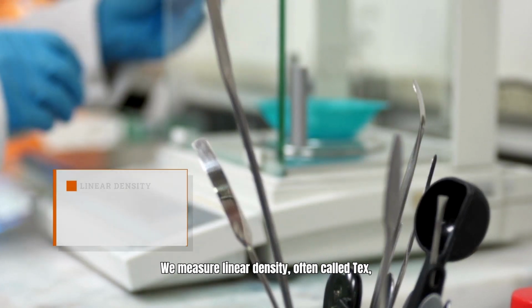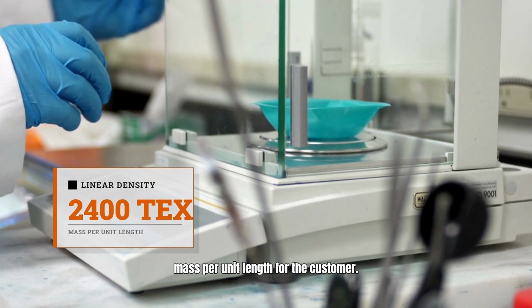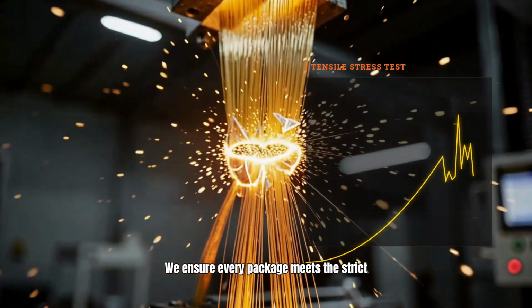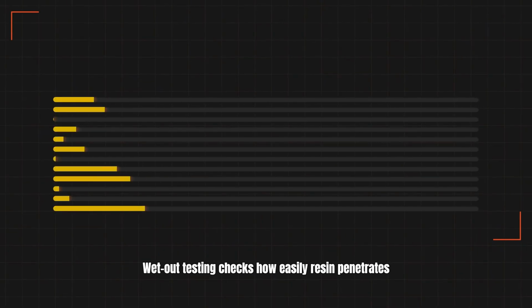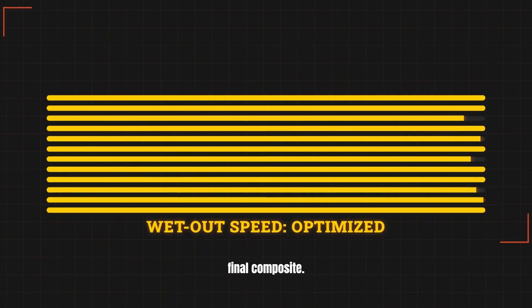We measure linear density, often called TEX, to ensure the strand has the correct mass per unit length for the customer. Tensile testing measures the true limit of the material. We ensure every package meets the strict standards of modern engineering. Wet-out testing checks how easily resin penetrates the fiber. Poor wet-out creates voids and weakens the final composite.